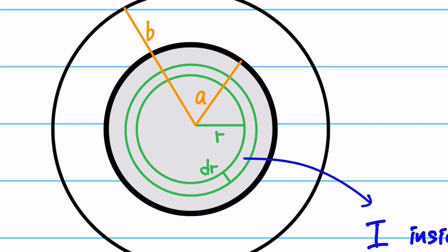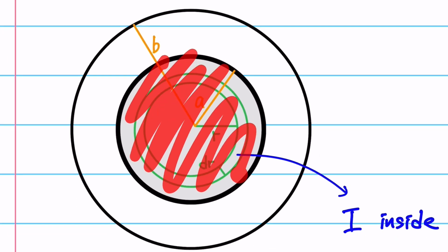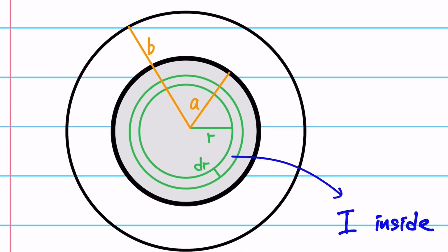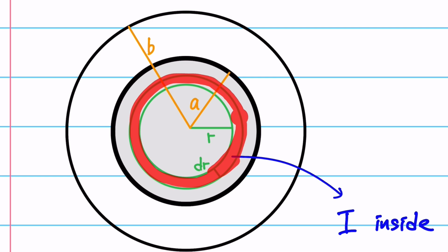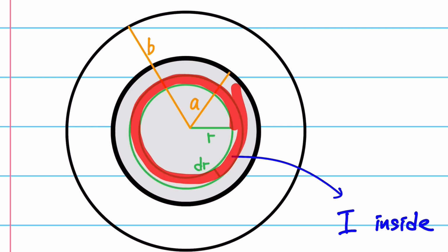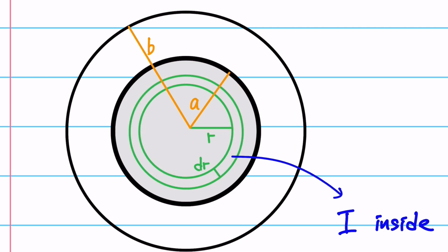If you look at this gray conductor, this is a magnified version to illustrate it. If you look at this thin central conductor closely, you can dissect the current. The current is flowing into the plane, into the screen, but we can now dissect this thin conductor into very, very thin rings like this. This is just one ring, and it has the radius of r, and the thickness of that ring is dr. That's where current is flowing.